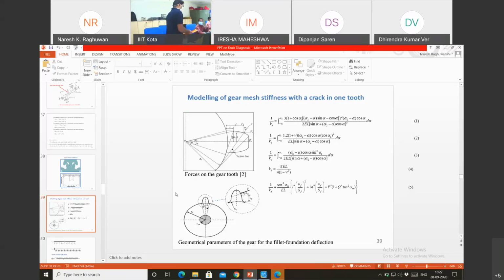Sometimes, sir, I have seen on gears that people provide some hole or elliptical kind of cavities throughout the gear thickness in order to increase the tooth strength. We consider the tooth as a cantilever beam, and when analyzing the tooth, by providing this kind of hole or ellipse, does the strength really increase in dynamic operations, or is it just theory?